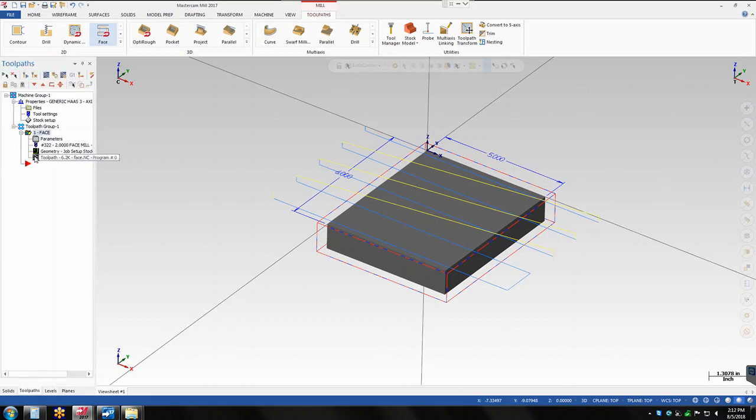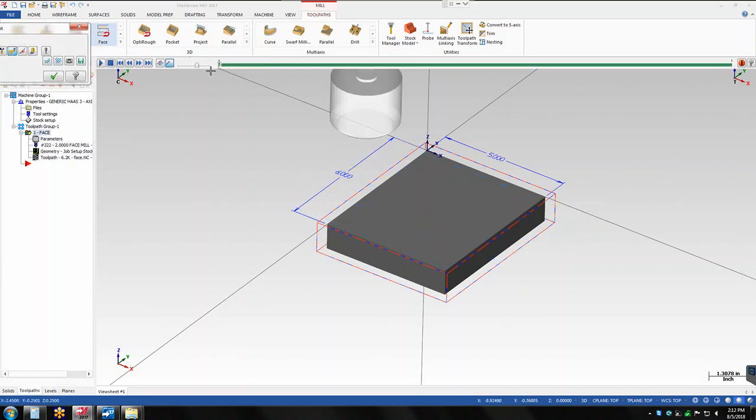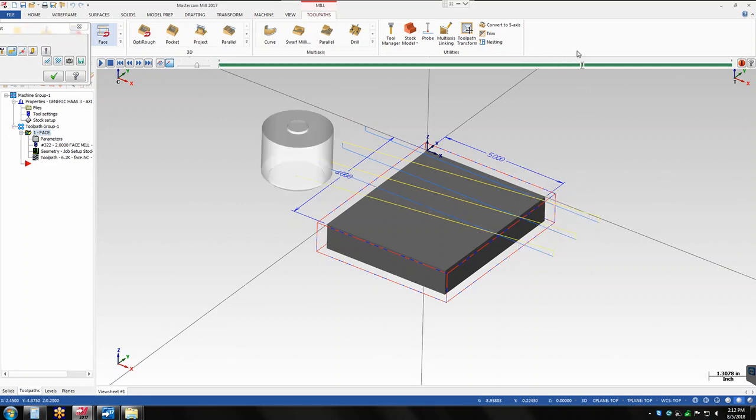Tool path, and as you can see, it's going to face, wrap it down, face. It's going to get to the end. It's going to wrap it up, relocate by the specified amount of step over, wrap it down, feed across, and at the end, it's going to reverse directions and cut the opposite direction on the last pass. That last pass, reverse direction,